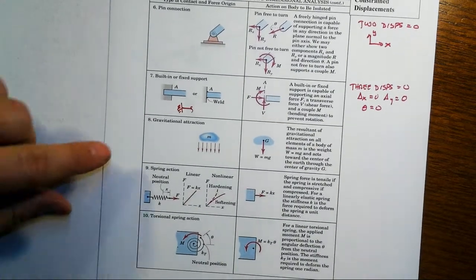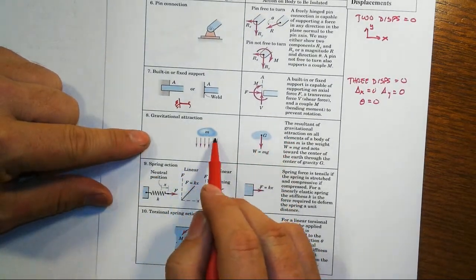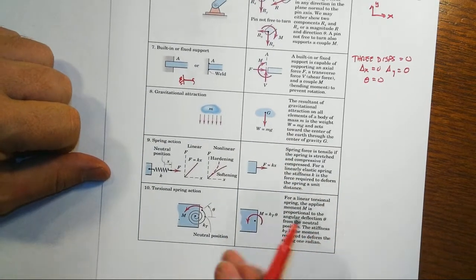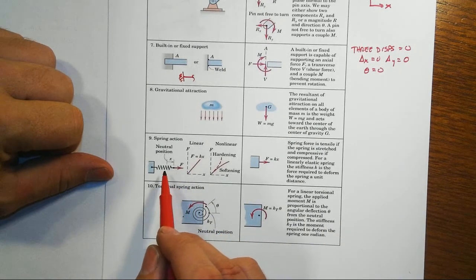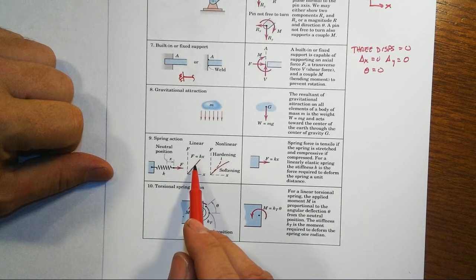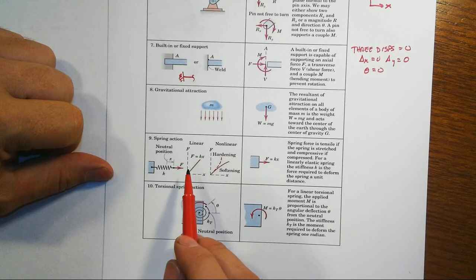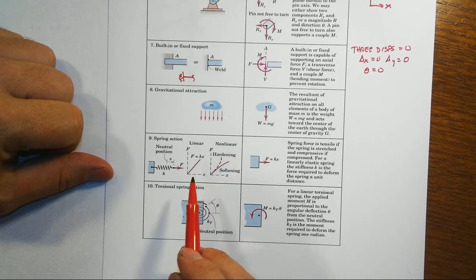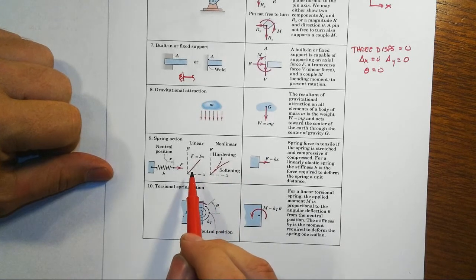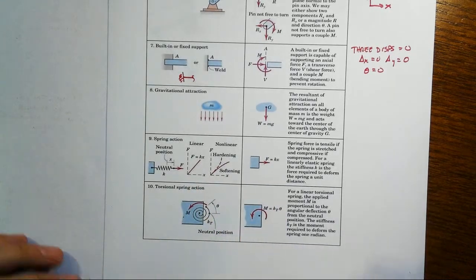Now, special situations here on forces and modeling. A body force is the gravitational force. We'll usually lump that all at the center of mass, W equals mg. If you have a flexible support that you're trying to model, well, then you'd use the F equals kx model for the linear model. It gets much harder if you have a nonlinear relationship going on there. So because of that, we oftentimes will do an approximate linear model when we have something that is nonlinear. Certain soil conditions might be like that. Certain elastic polymer elastomeric bearings can be like the nonlinear kind of system. And this adds some complexity to the system depending if we're statically determinate or indeterminate.